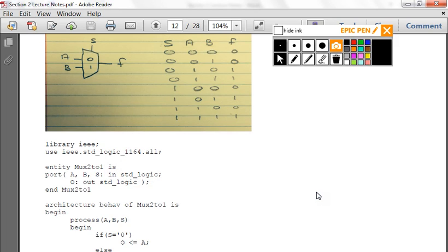You don't have to write tri-state underscored INV on the exam, time is short. TSI, TSB works fine as long as they match. And not is what does inversion. It's the primitive for inversion in VHDL. Any other questions?